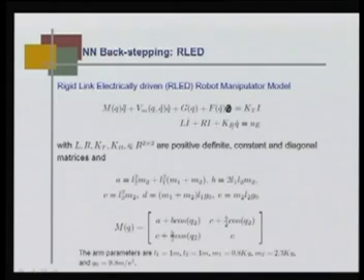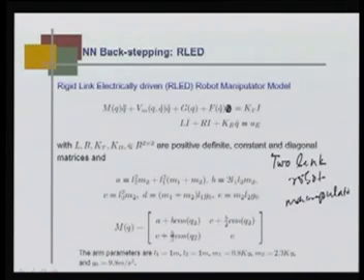which is the applied voltage, right. And by defining these parameters, A as this, B is this, taking a two link robot manipulator, and defining parameters A, B, C, D and E as this, M becomes a 2 by 2 matrix like this. The arm parameters are L1 is 1 meter, L2 is 1 meter, M1 is 0.8 kg, M2 is 2.3 kg, g naught is 9.8 meter per second square.